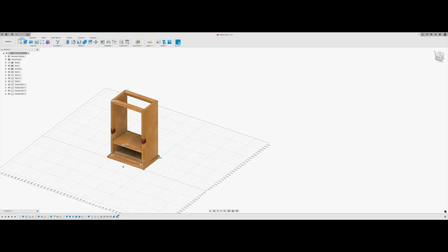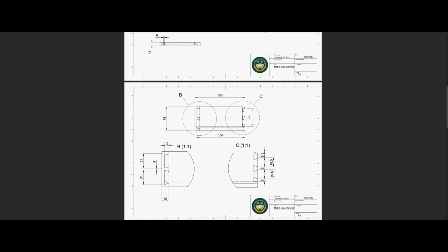Okay, so we're going to come through and we're going to draw our drawer. So if I flick over here, I'm going to start with this side piece, draw in my dovetails. Then I can duplicate it, draw my drawer front as a rectangle, draw my drawer back as a rectangle, use the combine tool to cut out the other half of my dovetails. Then I can add my base in, use the combine tool to cut out the slot for my base as well. So let's do that.